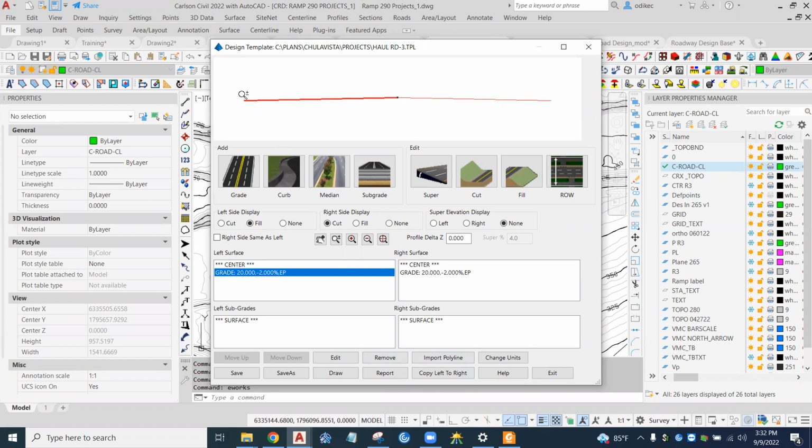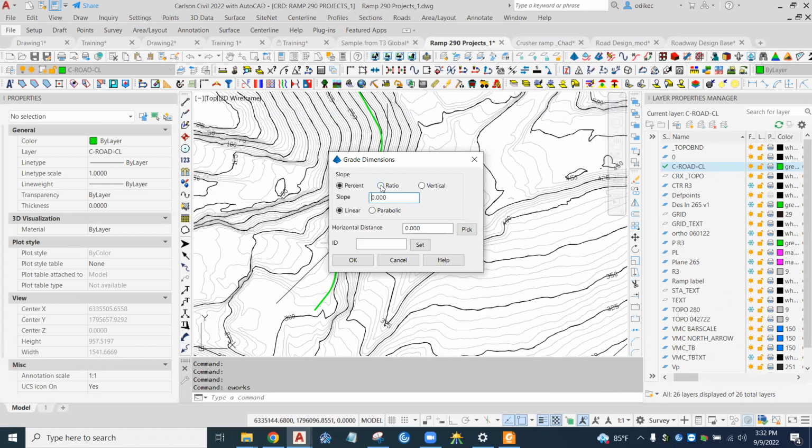So now this one's where the berm is going to be, yes, because that's my fall away slope. All right, so if I add that as a ratio, you say it's a 3-to-1? Yeah. So 3-to-1, and how high is it? I would say 3 feet as well. So if it's 3 feet tall and it's 3-to-1, that's 9 feet away. 9 feet, yeah. And so we're going to call that BRM1.